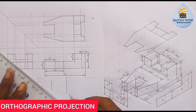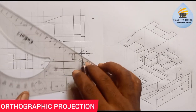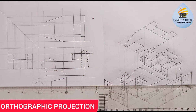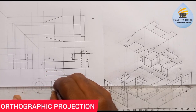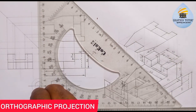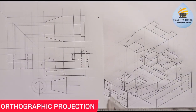And you connect this to this. And you also connect this to this. Can you see that? And you now draw your center line. So the meaning long, short, long, short, long, short, long, short, long. And you come here. This also long, short, long, short, long. So this is your symbol of projection telling you that it is in third angle projection.